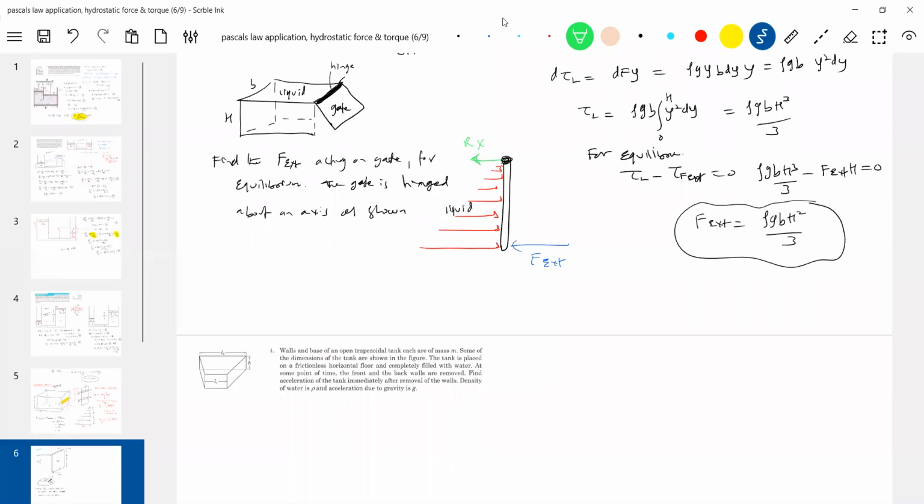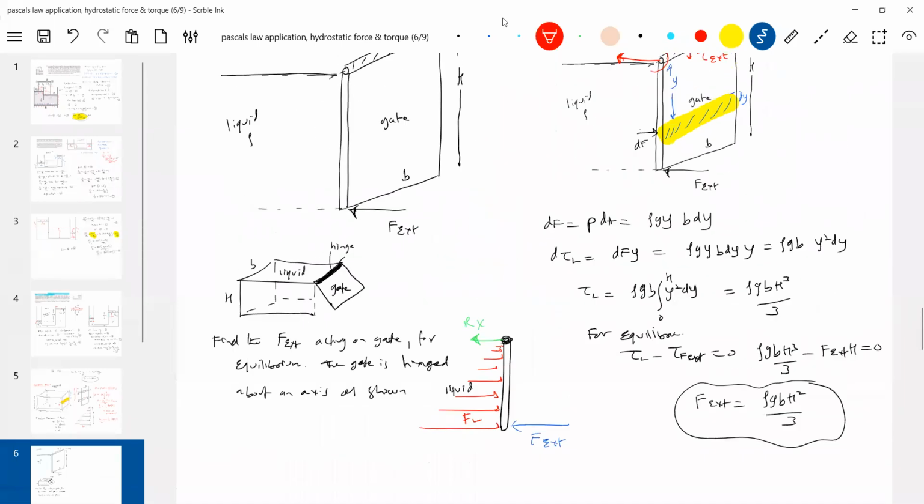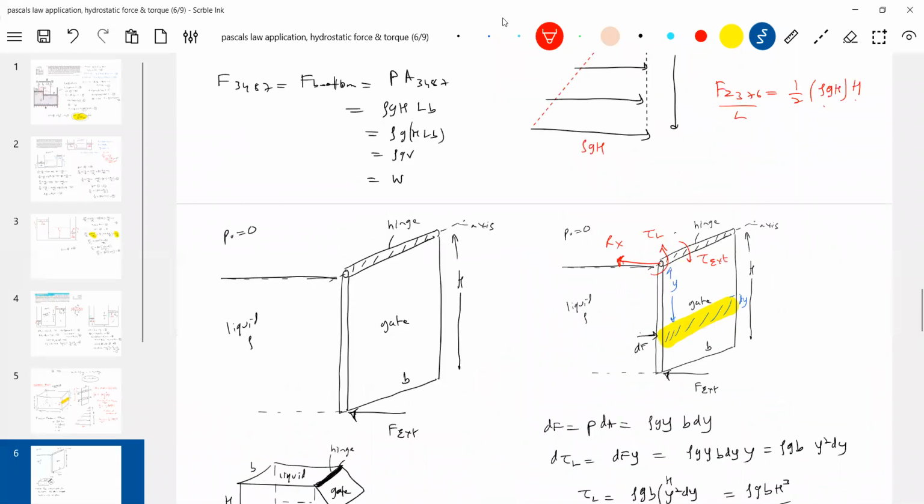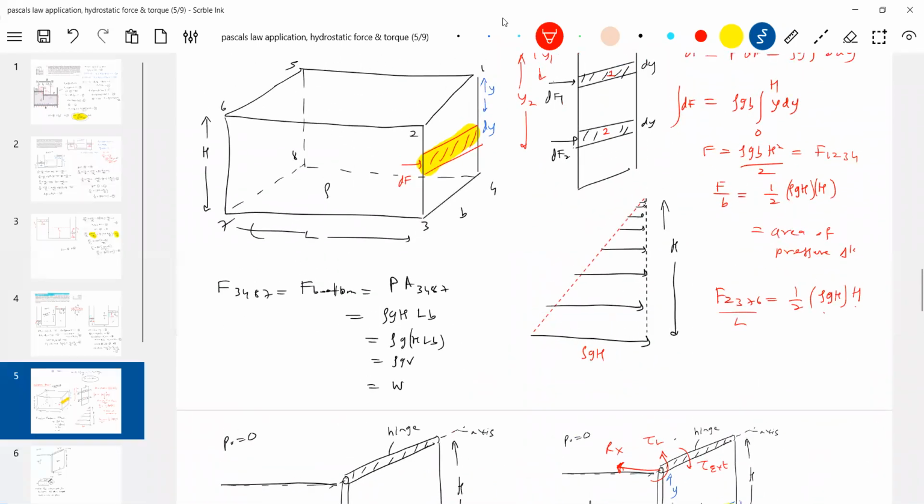It will be really challenging for students to make imagination. You are supposed to do it. How to calculate the force exerted by the liquid? I'll write FL. I don't know that value. Let me call that FL. Can we use the basic formula? What is the total force exerted by the liquid? Force per unit width is equal to the area of the pressure triangle.